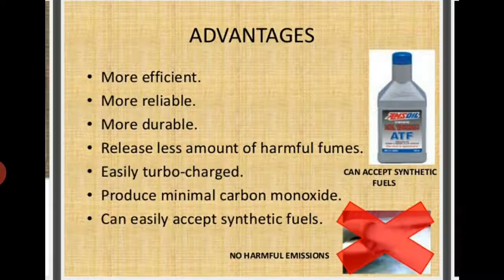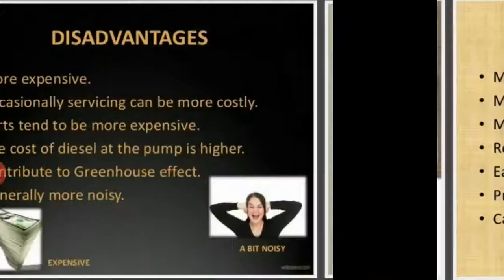The main advantage of the 4-stroke diesel engine is that it is more efficient as compared to the 2-stroke diesel engine, more reliable, more durable, can more easily accept synthetic fuel, produces a nominal amount of carbon monoxide, and releases less harmful gases as compared to the 2-stroke engine, because it is more efficient.